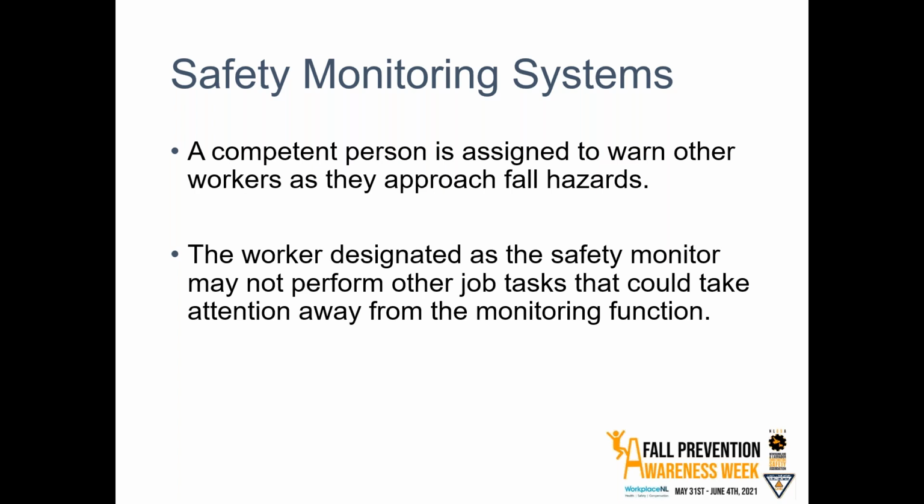Now, moving back to our other types of roofing work, in addition to the flat roofs, there are all kinds of requirements for roofs that are pitched. I didn't want to get into them in too much detail today, but generally speaking, there are 3 categories of pitched roof. With the lowest category, 3 on 12 to 6 on 12, you have 3 options for protecting workers from falling. You can put a guardrail all the way around the edge of the roof. You can fully deck scaffolding all around the edge of the roof. You can use toe boards and things like that in conjunction with that. And then you also have the option to use fall arrest.